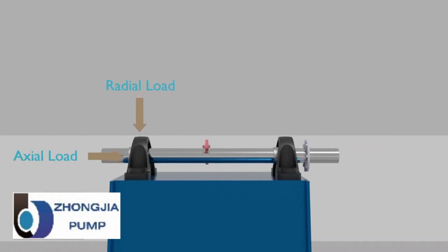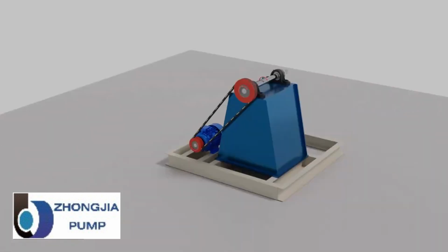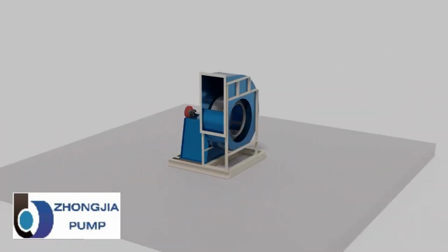Bearings are connected to the shaft. Bearings will allow the rotational motion, and they support both axial and radial fan loads. Another end of the shaft is fixed on the impeller, which allows power transmission. As a result, the impeller rotates at the speed of the driven pulley.